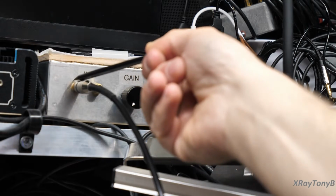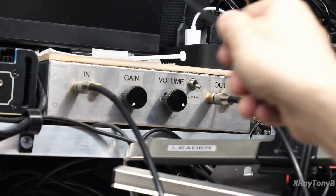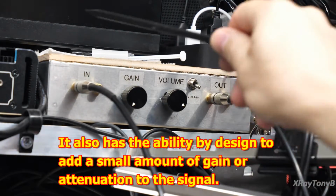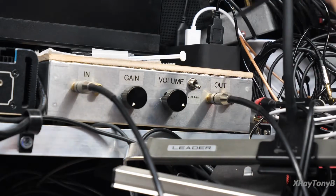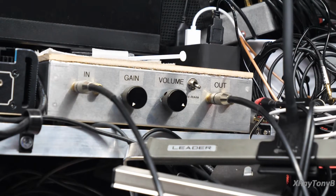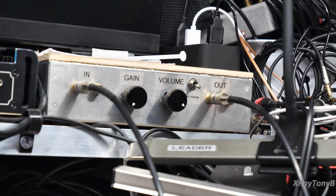So whatever I put into here comes out the same amplitude out here, but it separates the impedance between the two. So no matter what the impedance needs to be here and whatever load impedance here, one does not affect the other. That's the whole thing. It also prevents noise from crossing over in between the two channels, or the input and output.